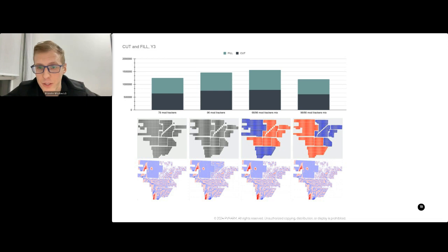So initially when we ran this, we thought, okay, we will use shorter trackers where we have steeper slopes, and then we use longer trackers for the more flattened parts of the site. But that doesn't work that way, and there is no one-size-fits-all advice. And usually the best way to understand what's going on and what configuration is the best is to actually run a bunch of options and see the chart and see what we get.